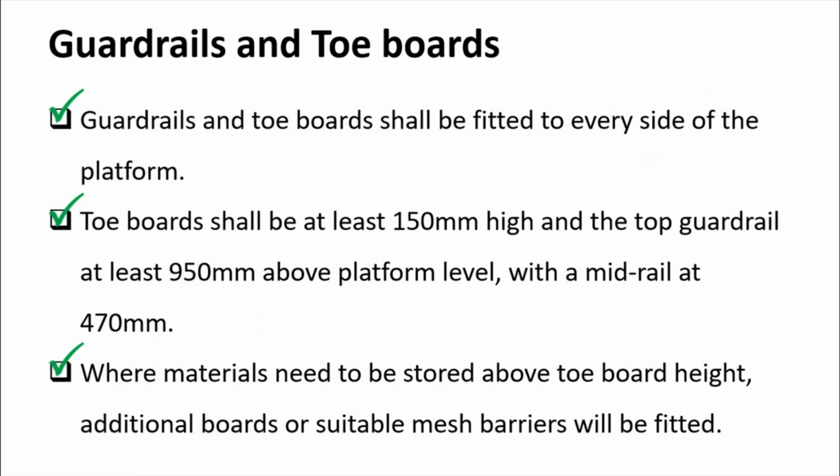Where materials need to be stored above the toe boards height, additional boards or a suitably meshed barrier will be fitted. So when you want to store materials above the toe boards, then you need to add additional mesh or barriers, so that the materials will not fall down.